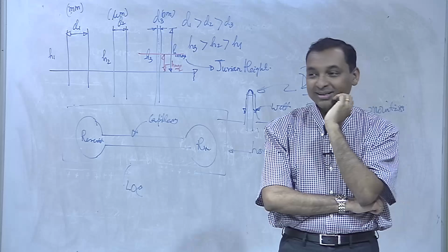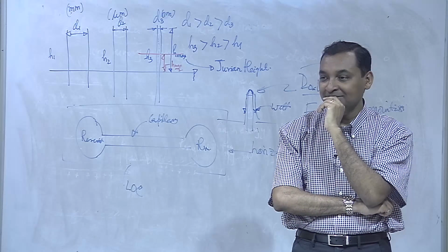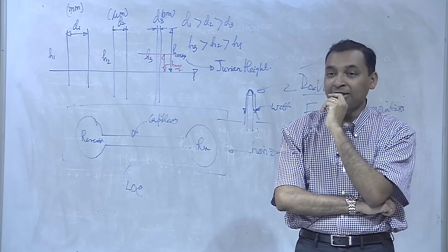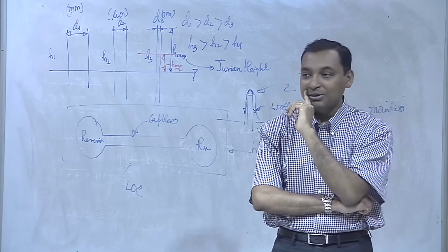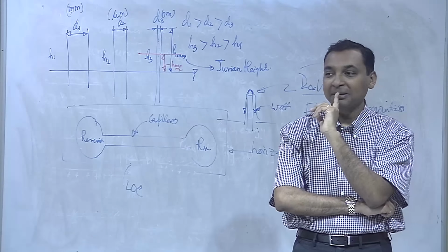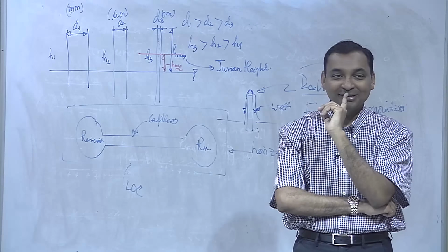The contact angle will also change. The gravity is not playing any role, right? So then will it not have a Jurin height, or what? H max will increase. A good point.